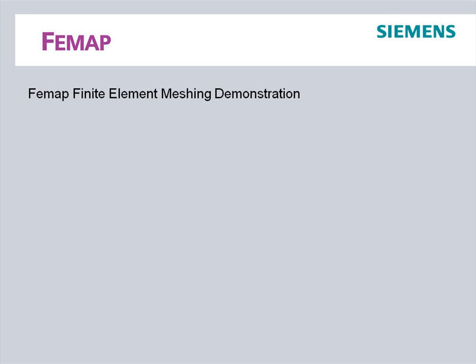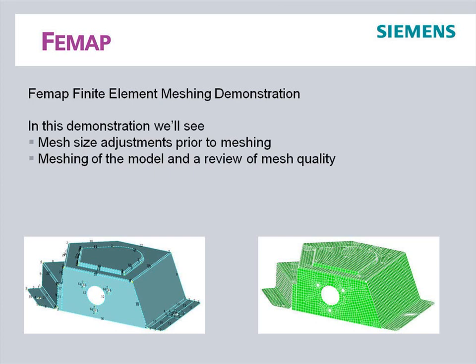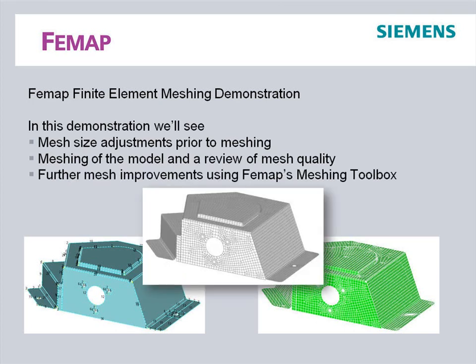Welcome to the Femap model meshing demonstration. In this demonstration we'll see mesh size adjustments applied to the model prior to meshing, the meshing of the model and a review of mesh quality, and some further mesh improvements after meshing using Femap's meshing toolbox.